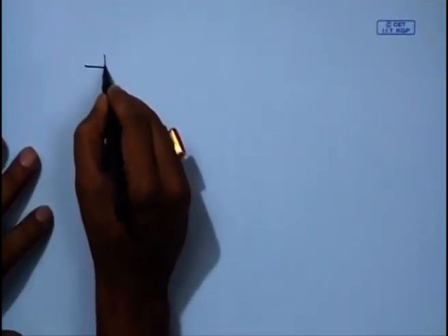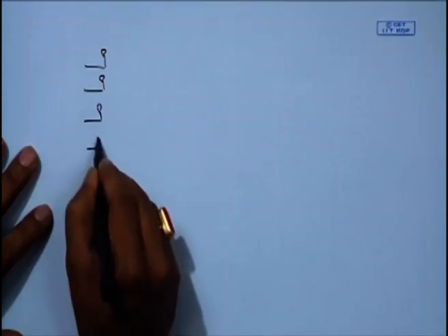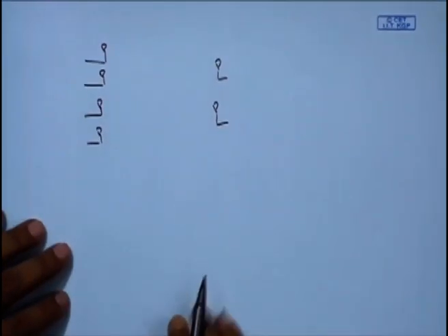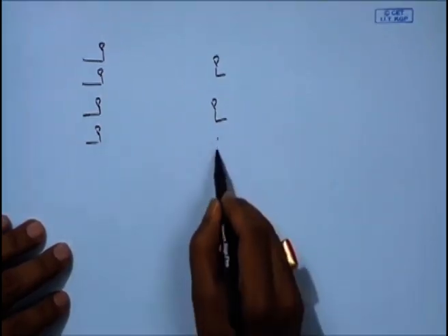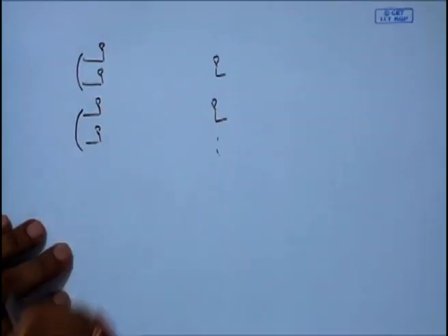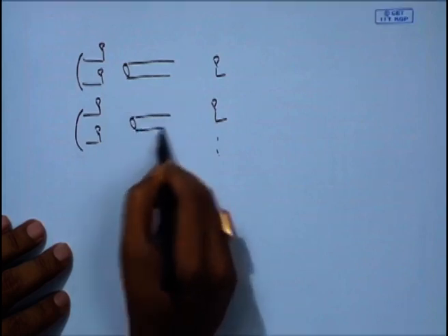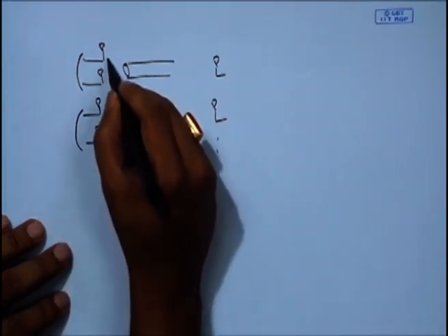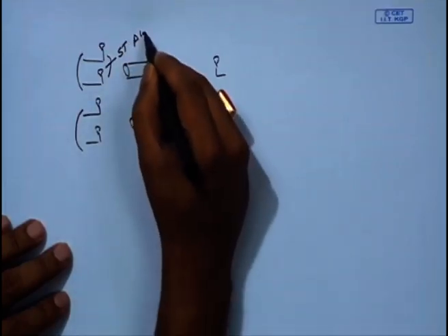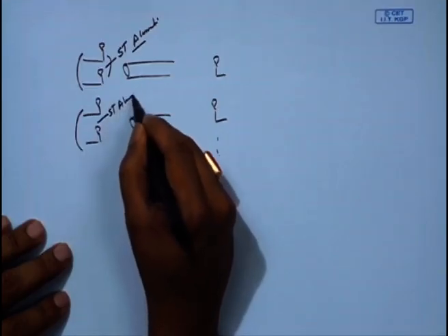One of the simplest schemes that we can talk about is the one where, as one particular example, there could be many, suppose I have a situation which has 4 transmit and 2 receive antennas. It can have more. What we could do is club these two and club these two, and say that I am going to set up 2 spatial streams, and in each of the spatial streams I could do space time coding, let us say Alamouti coding.